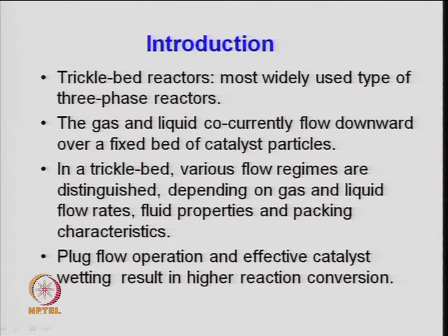So, trickle bed reactors are the type of reactor in which the gas and liquid flow from the top of the reactor, that is in co-current or counter current flow. And the basic idea here in the trickle bed reactor, if you compare it with a packed bed reactor, in the packed bed reactor also a similar operation is done. The only thing is that the trickle bed reactors are mainly governed by mass transfer operation. So, a larger size of catalyst particles are generally used in this kind of reactor. Another thing is that the flow rate of the liquid is low. So, it trickles on the surface of the solid.